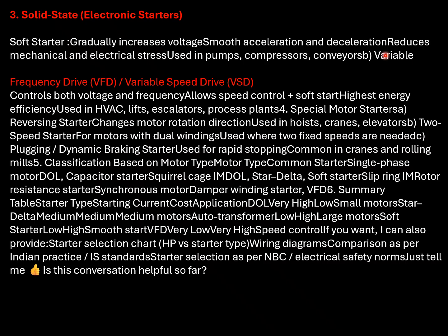Next category is variable frequency drive, VFD, variable speed drive. Controls both voltage and frequency, allows speed control. Soft start, highest energy efficiency, used in HVAC, lifts, escalators, process plants. Fourth, special motor starters.